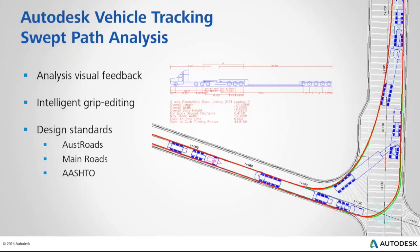Once we have our swept path in place, the object is an intelligent object which has grips that we can easily edit and refine the vehicle path as the changes are made, and these results are dynamically displayed and updated in your viewport.